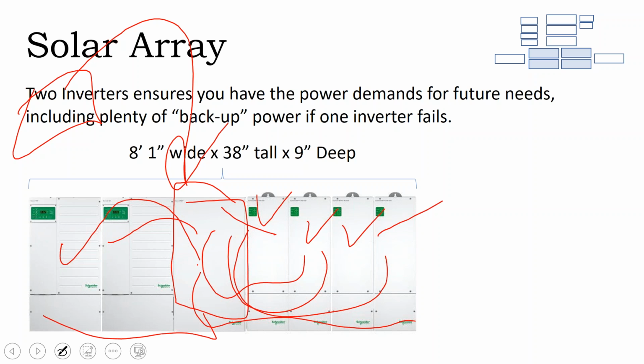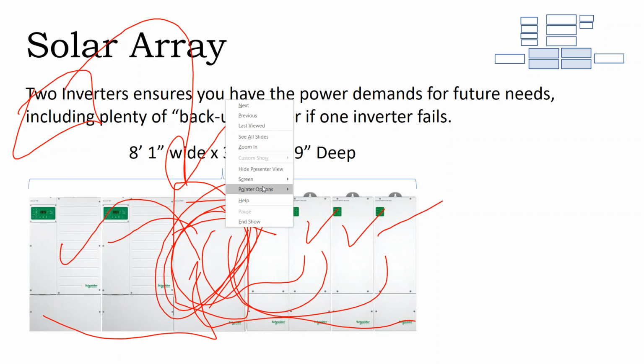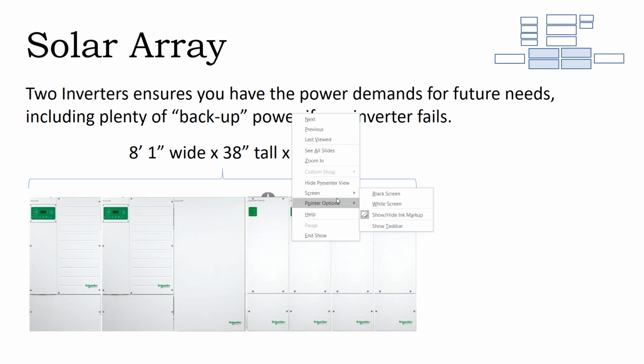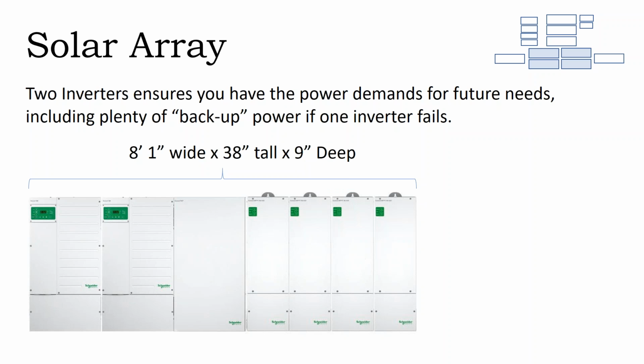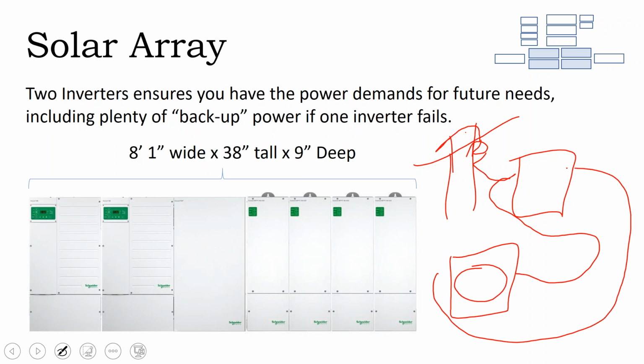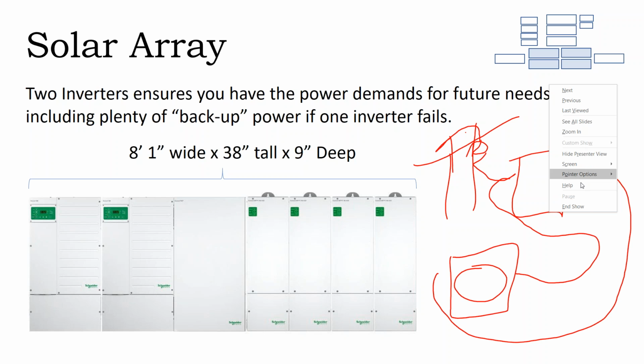And there's a little bit of wiring that occurs here too, but this is your line side master service panel. And I recommend not doing load side connections where you go into your existing panel. Let me draw this a little bit better. Here's your power lines coming in from your utility, and you've got a little utility transformer. The power lines go into your building. And then on the outside of your building, you have your electric meter. So you have the power lines coming in to the electric meter, and then you go into your building. It's a terrible layout.